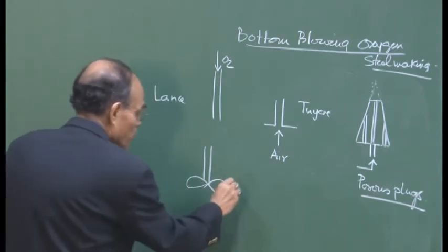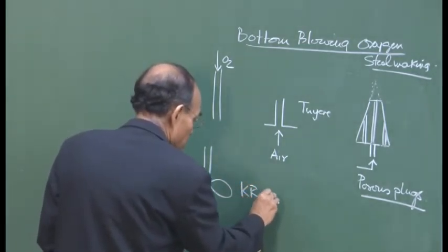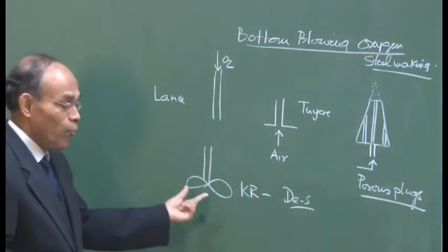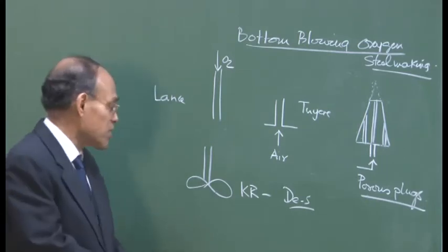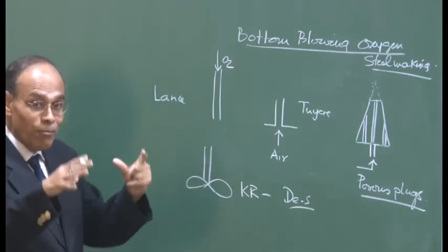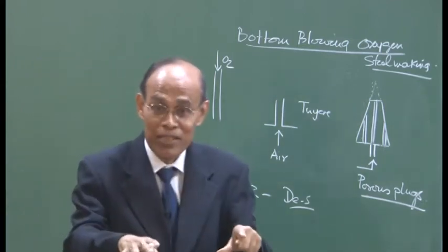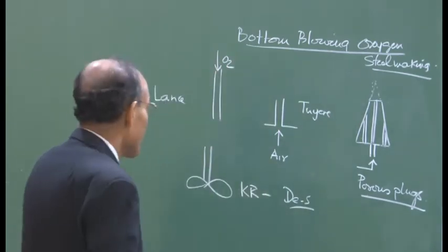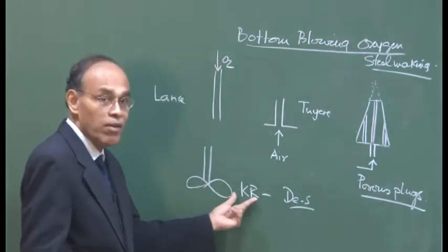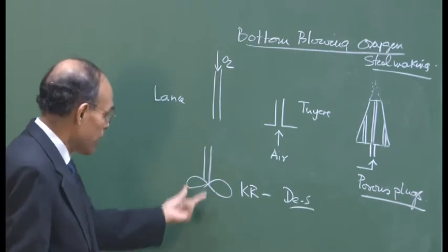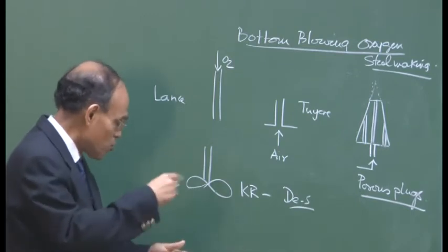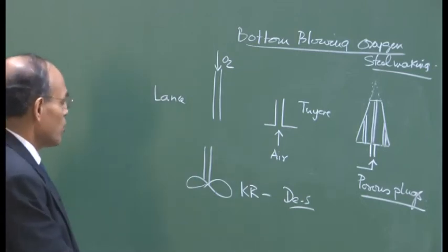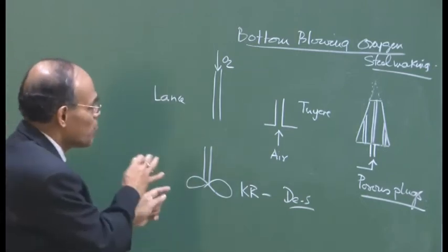For example, there is the KR process of desulfurization. This is a pre-treatment process where one would use an intense amount of stirring, because the hot metal temperature is going down. So, you want to impart stirring as early as possible. You require far more efficient stirring, and therefore the KR process uses an impeller to stir the contents for desulfurization, where you want to mix the powder, liquid and all the desulfurization agents. But that is besides the point.